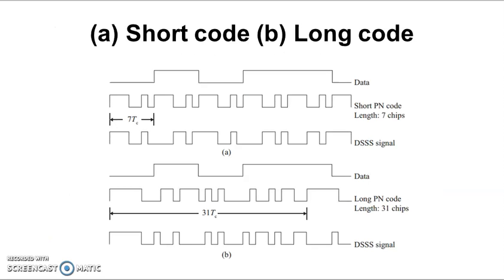Now for the given PN sequence, we know that the period is equivalent to the data symbol period. Codes with period shorter than or equal to the data symbol are termed short codes, and these codes repeat for each symbol. L chips of the PN code are contained in each data bit duration TD, and with each chip duration TC, we have L times TC equal to TD.